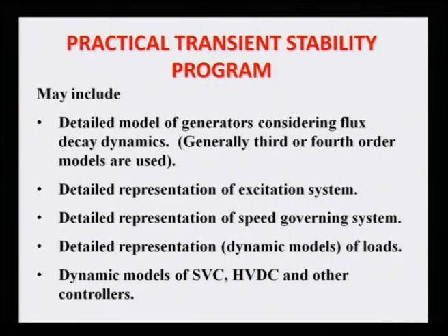Last but not least, if you have any FACTS devices, including TCSC and static var compensator, that is SVC, or HVDC systems, those controllers should also be modeled in the transient stability program, because they affect the stability of the system by their control action. Whatever other controllers are there, they should be modeled in detail. We will see all these modelings one by one, and then finally combine them together.